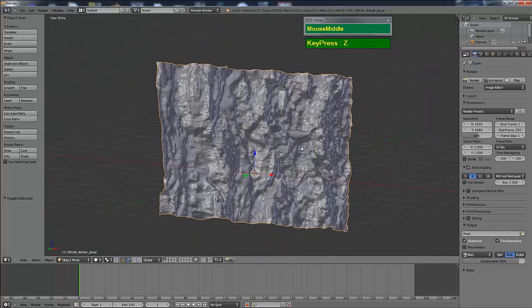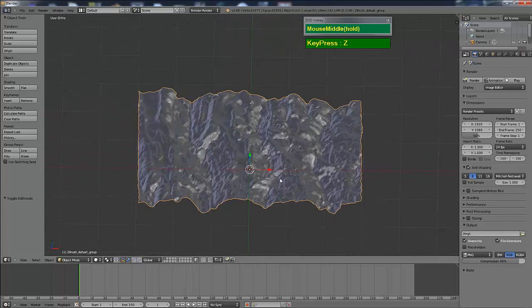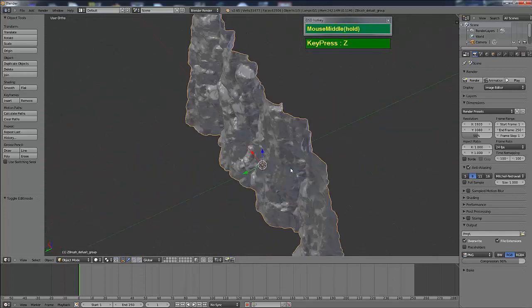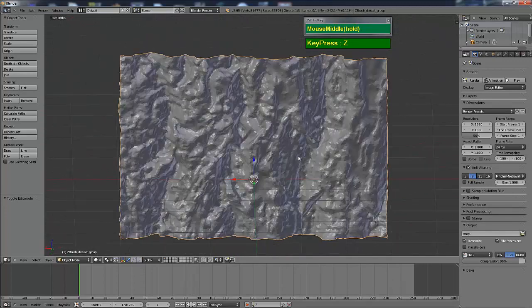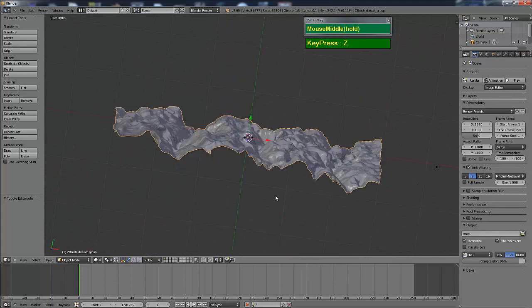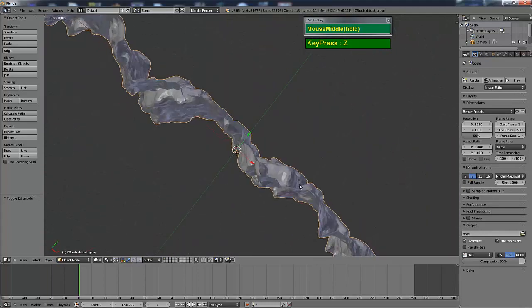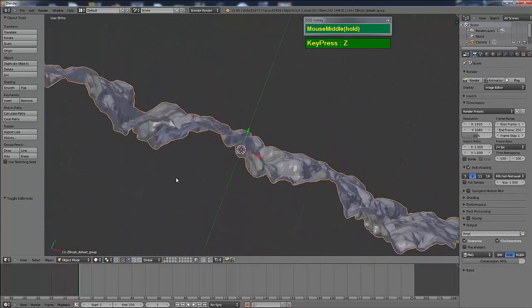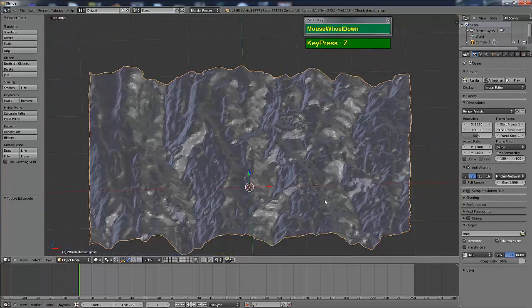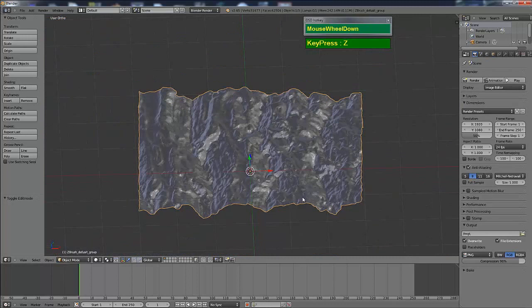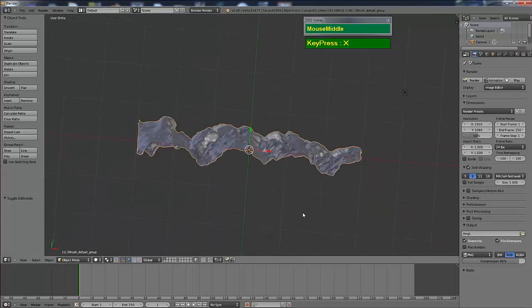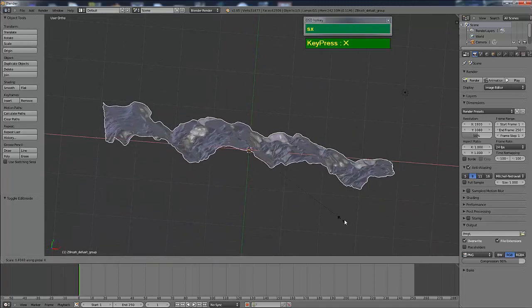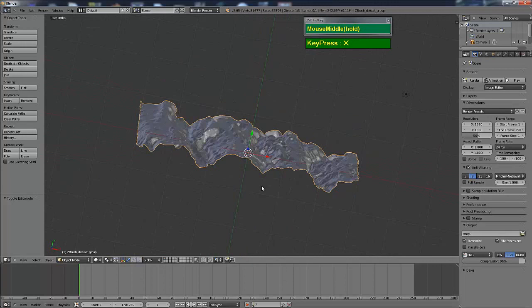The next thing I want to do is scale and flatten this piece a bit, because later when I'm trying to thicken this, I do not want to have too many of these overlapping meshes. So I'm going to scale along the x-axis, S followed by X. Now you notice that when I follow with X, it's scaling along its original local axis.